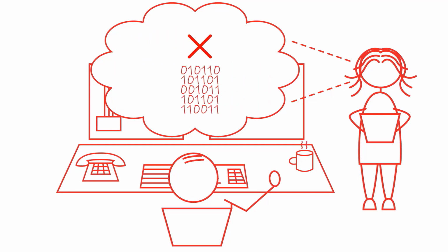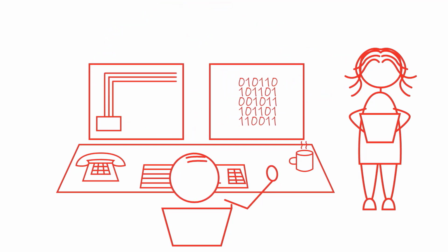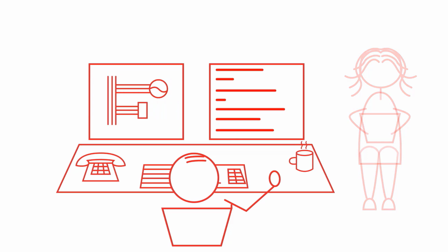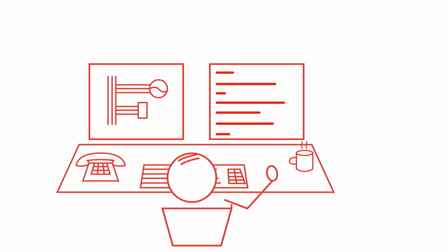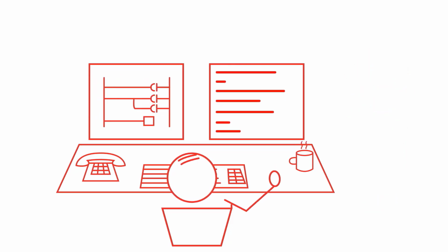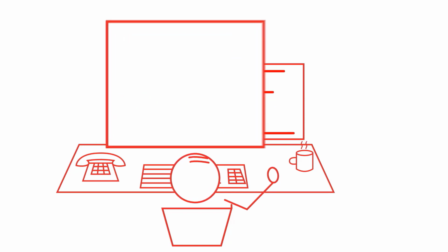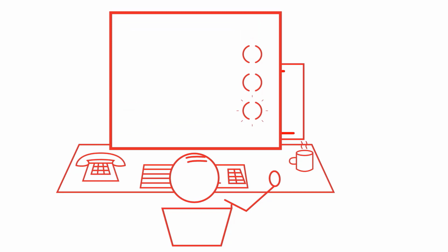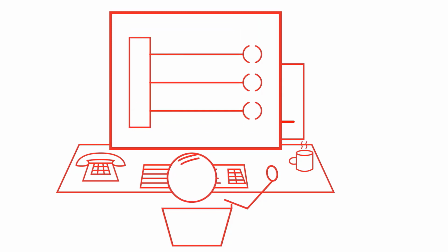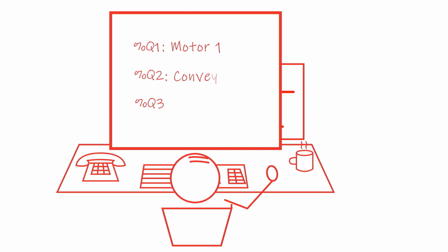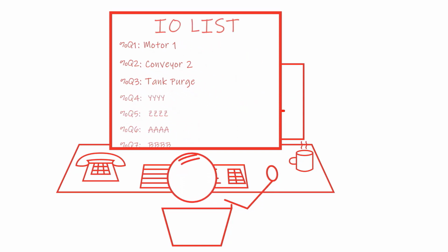Of particular interest is the crossover point between the schematics and the PLC. Again, we make some assumptions. We assume that we know the capabilities of the controller. We assume that we have clarified all of the interfaces. We have the right input-output cards, memory, scan time, all of the hardware, and most importantly, and why it is at the end of the list, documentation, and which I/O address goes to which device. How do we organize our tags?